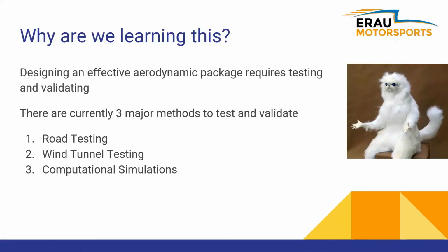So first things first, why are we doing this? Well, designing an effective aero package requires testing and validating the capabilities of said package to analyze the effects it has on the incoming airflow and look for possible improvements based on your design requirements/goals. Currently, there are three ways to test an aero package. There's road testing, there's wind tunnel testing, and computational simulations.